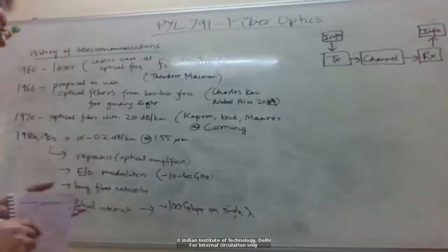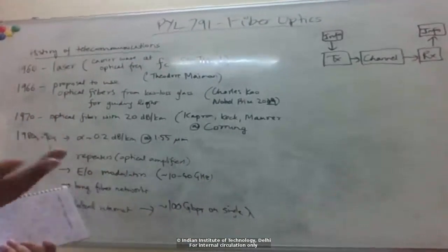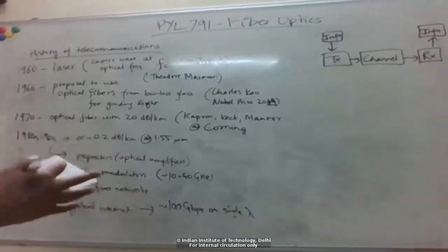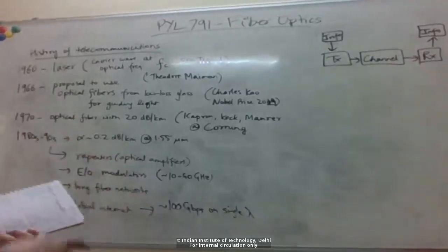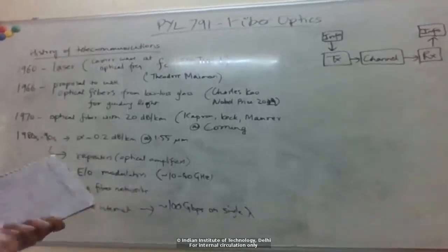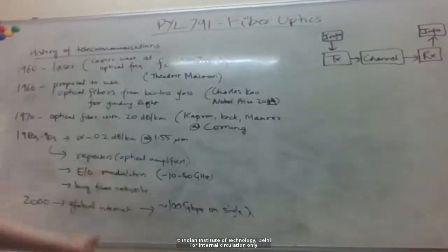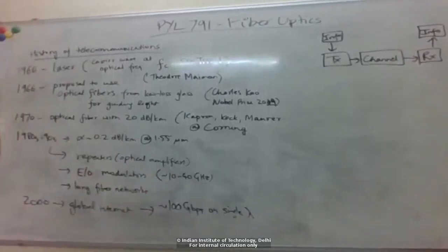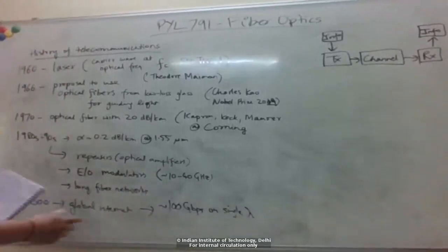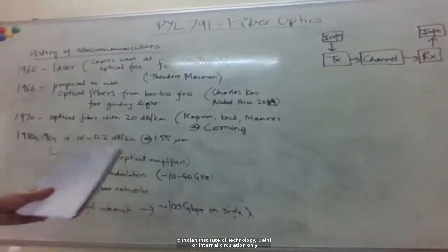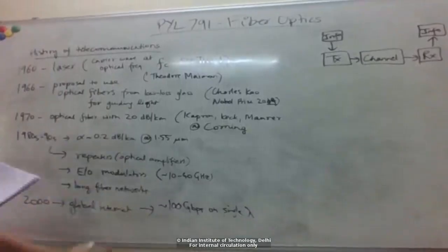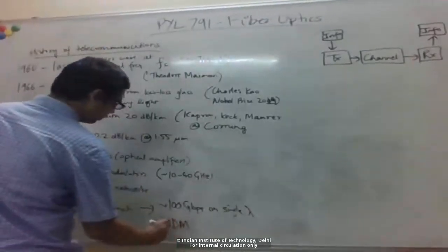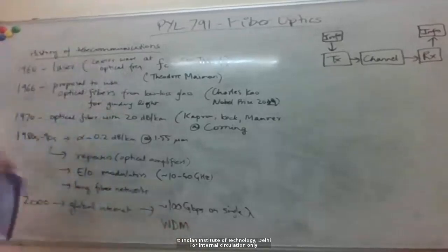That's a big problem in, for example, our mobile networks and RF transmission: there's a lot of interference from background signals, noise, etc. But because these optical signals are at such high frequency, there is actually no other noise to interfere with them. Okay. And you can also send multiple wavelength channels which don't interfere with each other. That technology is called WDM, or wavelength division multiplexing, right, to send multiple wavelength channels.